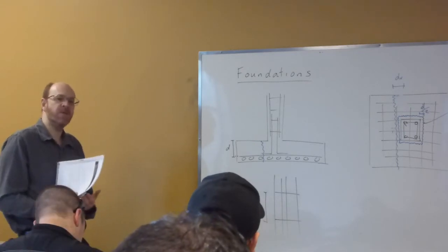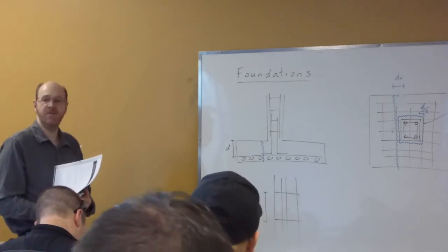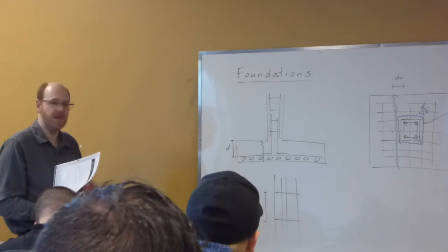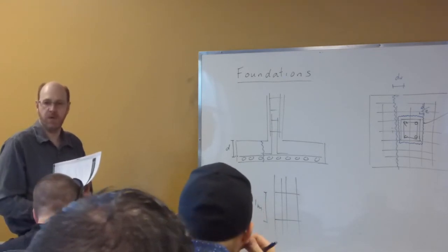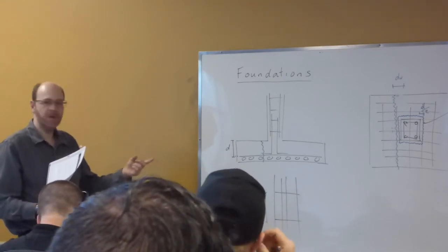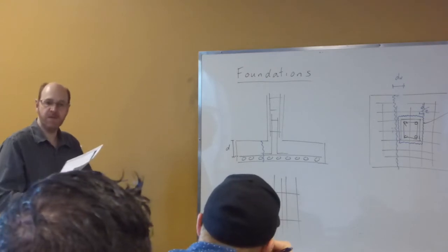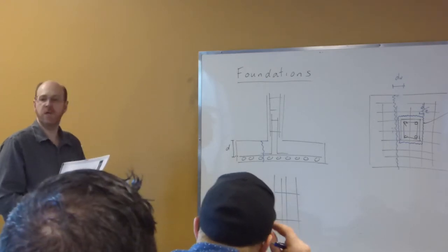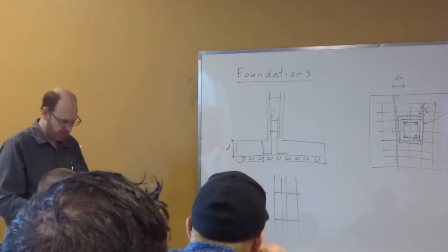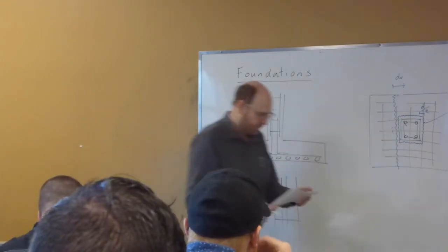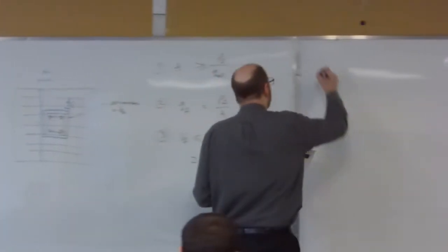And then once I've got my thickness, I can calculate a DV. We've got two separate formulas for DV, and then I can go and check my one-way shear. So we use our two-way shear to come up with a D and a thickness, and then I check the one-way shear from that to see if it works, and if not, then I increase accordingly.